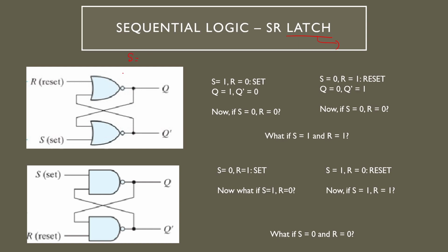For an SR NOR latch, the idle state is S equal to 0, R equal to 0. That means you can have an S input across time that looks something like this: flat zeros. And during this state, what is Q? Well, the correct answer is we don't know. Q actually depends on a state which has happened in the past. This is really important to understand.